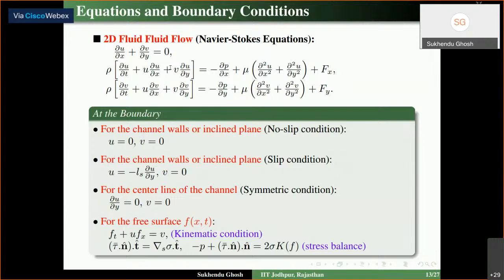So, to solve the Navier-Stokes equation, the only possibility is you have to impose some methodology to modify the equation or to find the limiting solution of the equation. That is the only possibility to solve the system of Navier-Stokes equation. Okay. So therefore, now I will tell you how to actually get a simpler equation from the Navier-Stokes equation and how to solve that simpler equation using linear algebra and numerical analysis. Right.